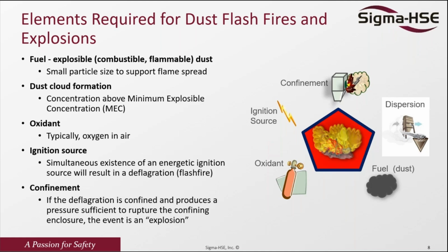Metal goes through heterogeneous combustion and organic goes through homogeneous combustion. For an organic solid, for example, if I disperse the material, the first particle will ignite. The ignition will give off energy. The energy release will move to the next one, then the next one will also move to the next one.